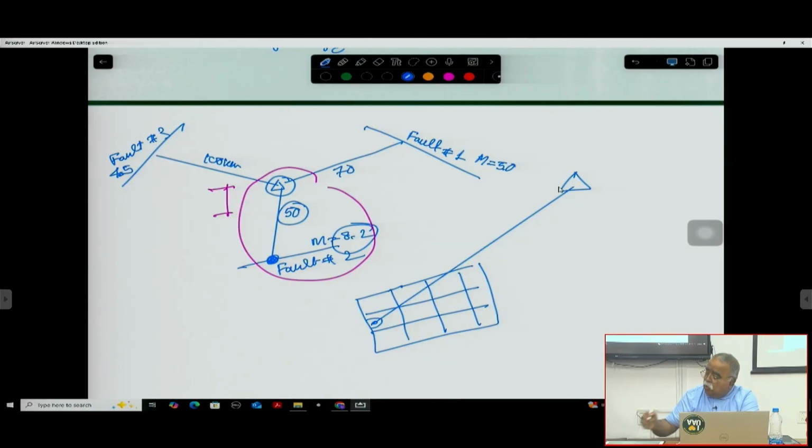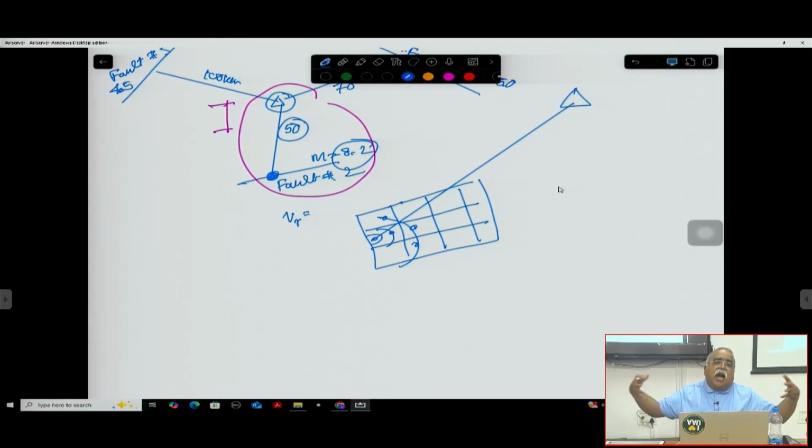Then we loop it over. We give the rupture some sort of velocity. So this is your rupture velocity, which you can decide, and then it reaches this point after 1 second. So then we can calculate these same things again, and then when it reaches here, all will be delayed by a time, and then you sum over all the times at this point. So that will be your finite fault model.